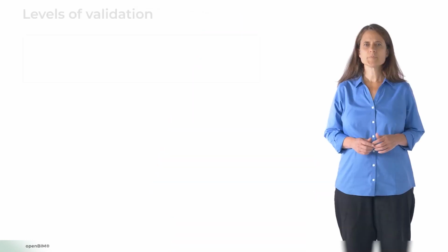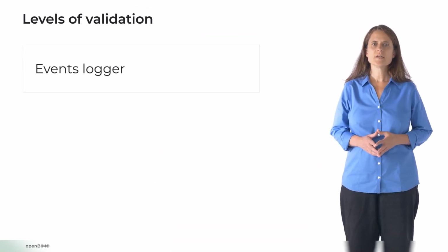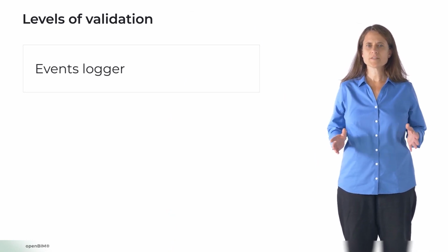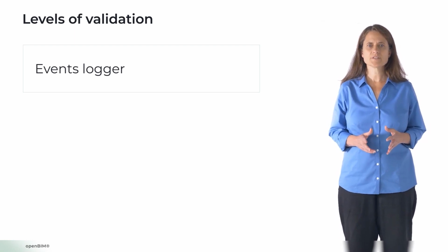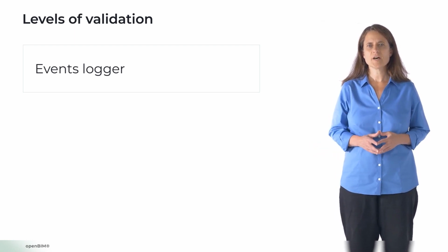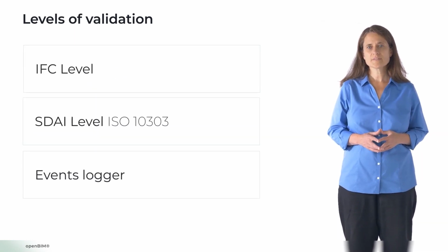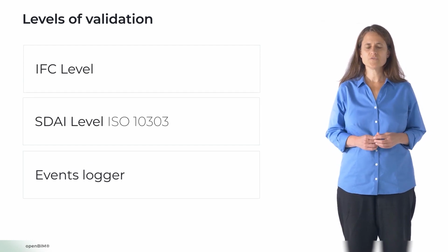During the development of our IFC SDK, we encountered a significant number of IFC files with errors of varying complexity, from basic syntax errors to topological errors with incorrect relationships between objects. The most basic thing that we can do for the industry is to provide tools that can report such errors. In some cases, it's possible to make implicit fixes, like transformation of non-instantiable objects into building element proxies. So an error logger is the lowest level of IFC SDK's new validation engine.